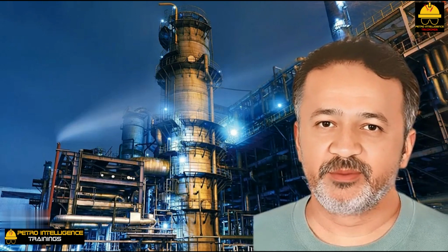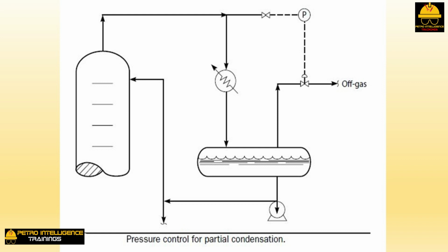Partial condensation. If we normally have a situation in which non-condensable vapors appear in the reflux drum, then there is only one pressure control option available. This is to place the tower pressure control valve on the vapor off gas as shown in picture. If we normally have non-condensable vapors in the condenser effluent, then the following problems we have been discussing do not exist: condensate backup, subcooling of condenser effluent, and fouling due to low flow of the cooling water in the tubes.